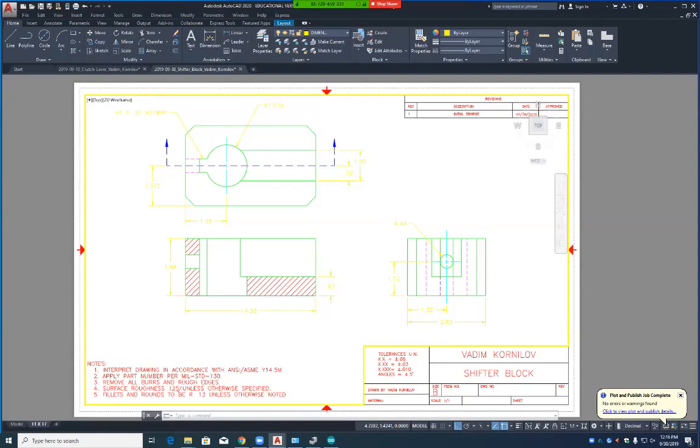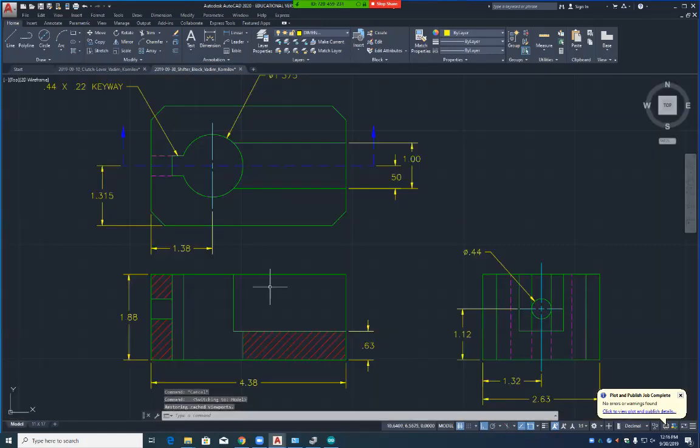Did you guys get a degree on the chamfer though? Oh, we didn't do the chamfer. Oh, add the chamfer there, I'm sorry, I forgot that one. We'll just do one of them and stick 4X. Can you just do a 45 and that's enough? Is that the 45, typical? So 45 typical, is that what that means? But then you have to have a distance too, don't you? I guess it's 45 from both.